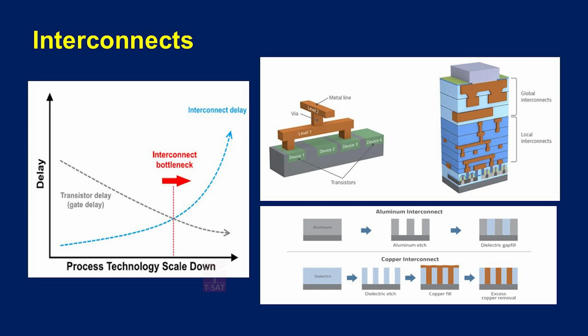Because of the denseness in the lower structure, the interconnect resistance is also increasing, right. And on top of that, the main problem we see here is the coupling between one interconnect and another, the overlap coupling capacitors, right.